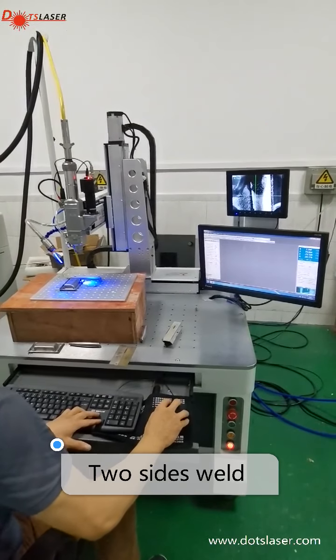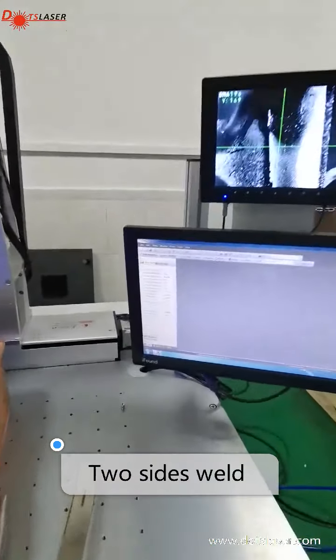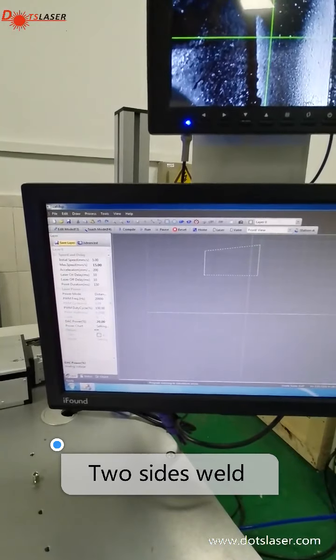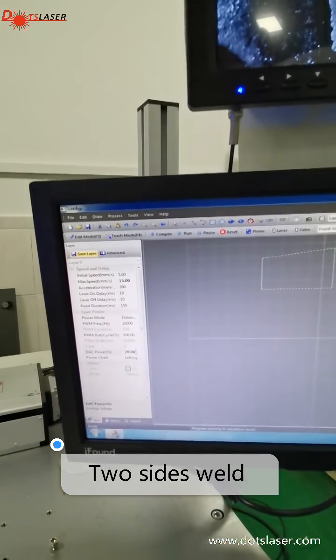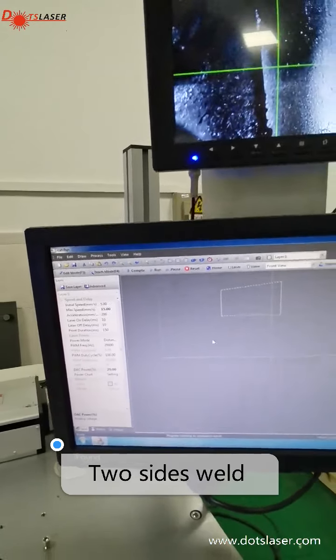Now we need to set the parameter. Please set the parameter. Because the metal sheet is not too thick, we set the DAC power, which is for the laser output power. So use 20%.